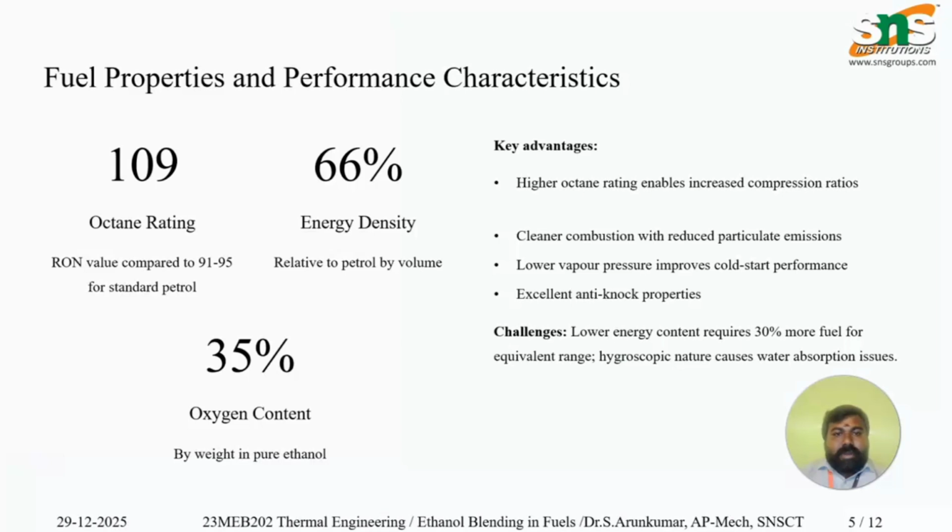Some fuel property and performance characteristics are an octane rating in the range of 109, compared to 91 to 95 for standard petrol, 66% of energy density relative to petrol by volume, and 35% oxygen content by weight in pure ethanol.